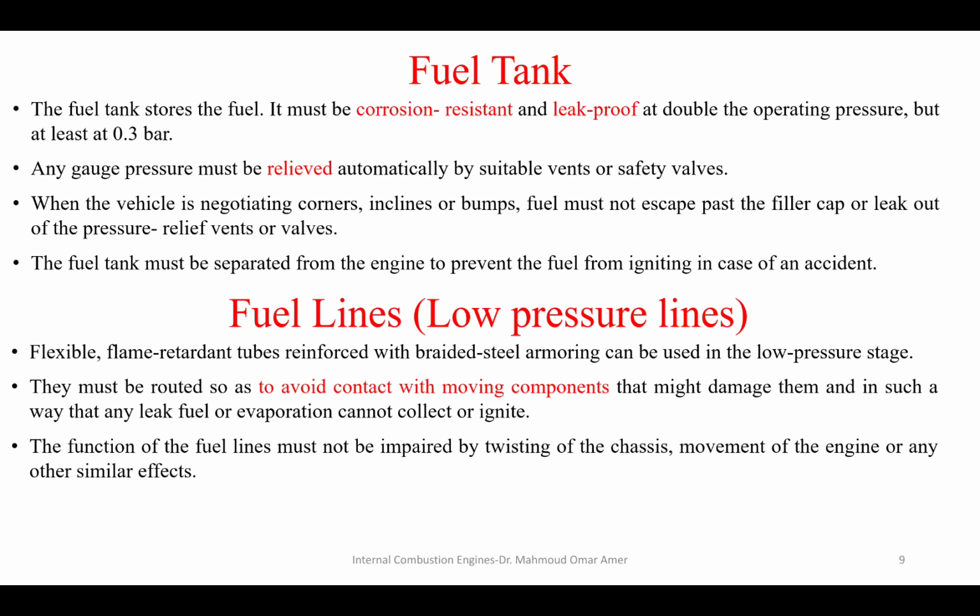Inside the tank, there are baffles to make the fuel stable inside the tank and not swing from side to side when taking hard turns. Also, in case of emergencies, or if the vehicle is tipped over or rolled over, the tank must be sealed and not release any fuel from it.